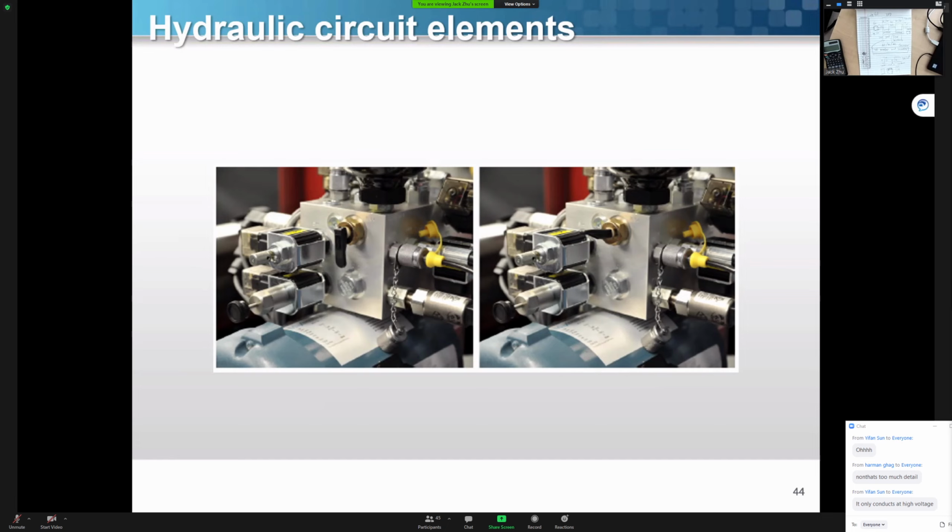It's called a metal oxide varistor. It has a variable resistance value. Only when the voltage goes over a certain limit will the resistance become really low. Okay, it's not my topic. I'm not going to say too much, but that's where they use them to protect the line.